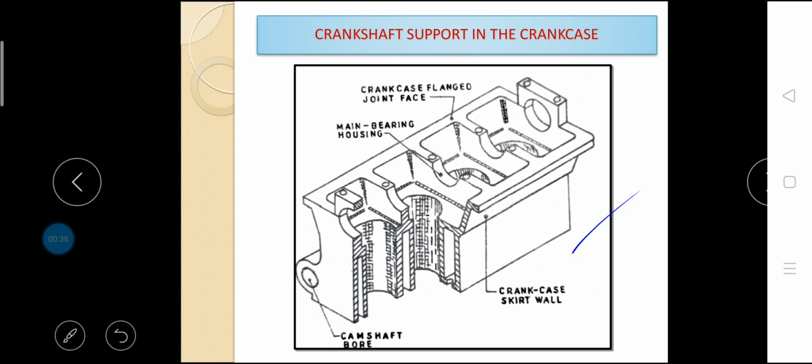Main bearing bores and camshaft bearing bores are aligned bored to allow these shafts to rotate freely. The center lines of all the cylinders must be at exact right angles to the crankshaft center line to avoid side stresses on pistons, connecting rods and cylinders, thus ensuring free movement of pistons. Likewise, valve lifter bores are also machined at right angles to the camshaft bearing bores. Cylinders in the block are machined and honed to a very accurate finish for good lubrication and proper ring seating. Cylinder walls are finished to a 1 micron finish with a fine rotating hone. An intersecting visible crosshatch scratch pattern is produced by the hone.